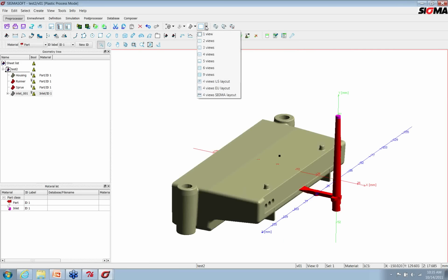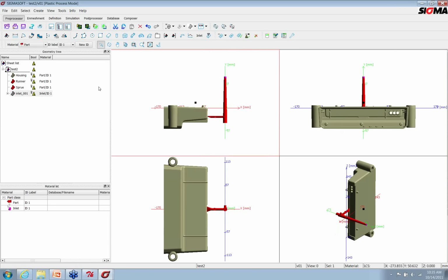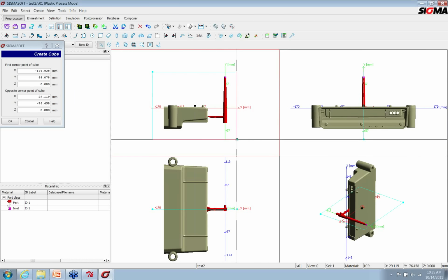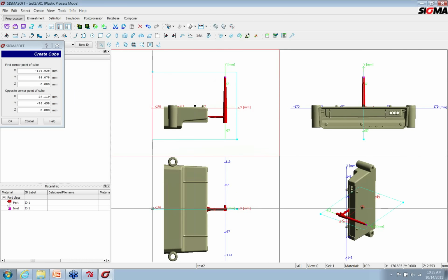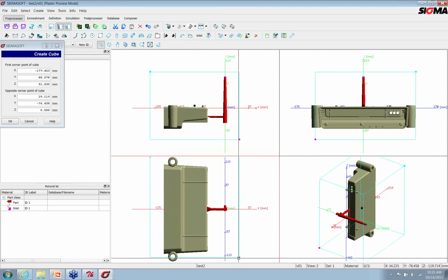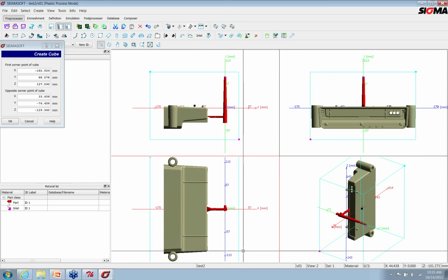Now I can go in and do the same idea as before. Now, you could even put two pieces of steel on. We could put an A half and a B side on here, or we can just do 1 piece of steel. But for today's example, I'm just going to keep it simple and put 1 piece of steel around it. And it's important, if you can be realistic, to capture these actual dimensions. So even if you don't know what the mold block's going to be yet, do something that's realistic, because in the calculation, we want to know the distance between that cavity through the steel, because outside of that steel is your ambient air, and the software is considering that.